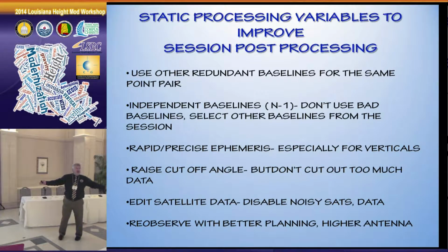You can change the cutoff angle. That's another thing I didn't mention. So instead of processing it at 12 degrees or 15, you can raise it to 20 and process again. You're eliminating more data though, aren't you? So you don't want to raise it too high or you don't have enough data, and even if it processes it, your statistics will be inflated. You don't want to trust that too much. So you want to keep it not above 25 degrees, I would say. Anyway, things you can do.